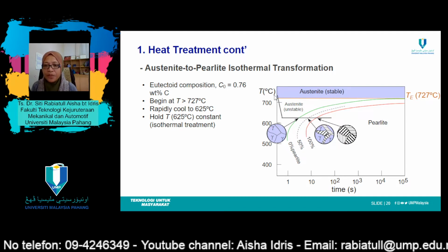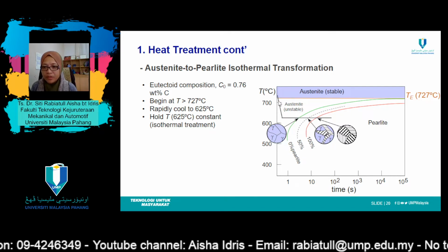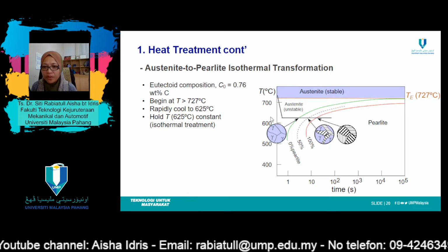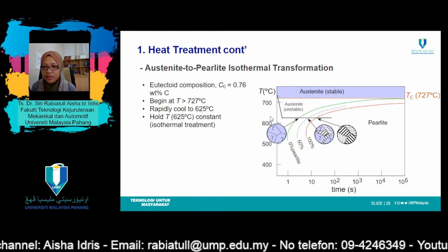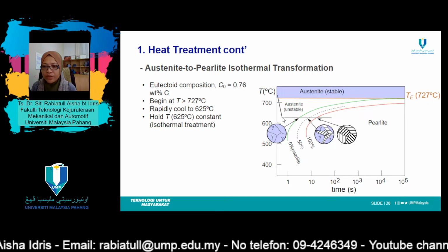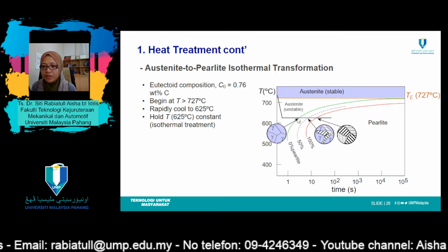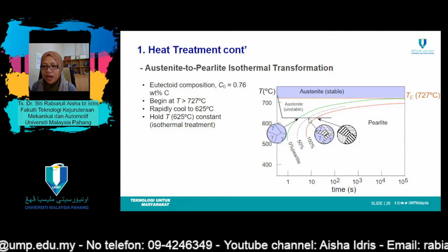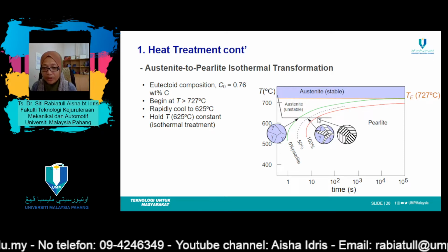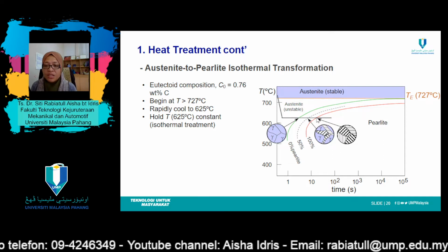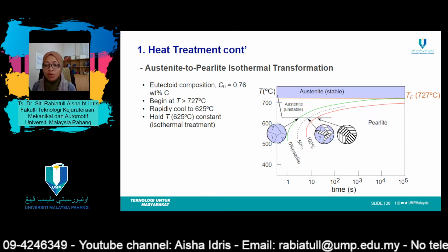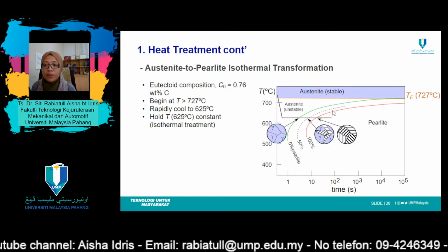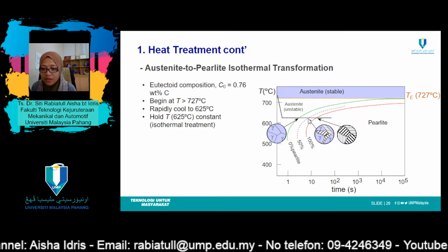Okay, again, start cooling. This line represents the cooling line, and then until it reaches the point 650 degrees C. So this is 650 degrees C, and hold that temperature until it reaches this one, 0% pearlite, reaching this line is 50% pearlite, and reaching this line is 100% pearlite. If we want to change the microstructure into only 50% pearlite, then the process should stop somewhere here at this line with a dotted line there. From there, finish it, cooling down.